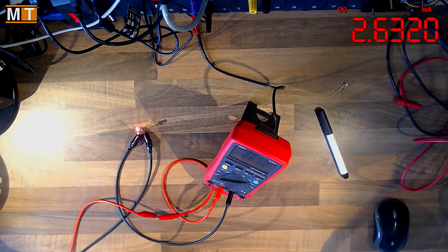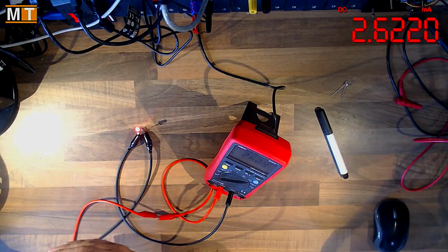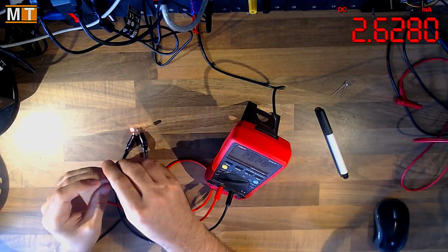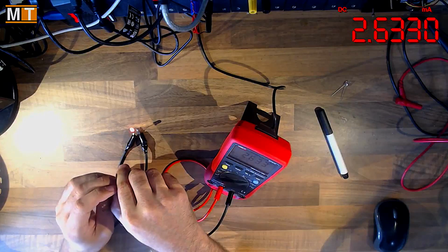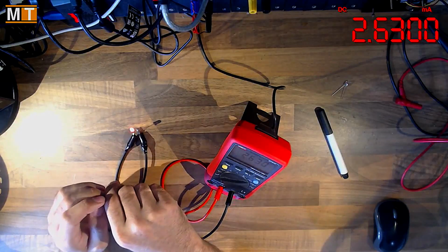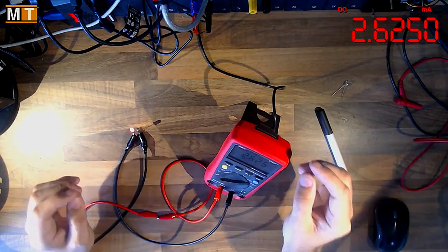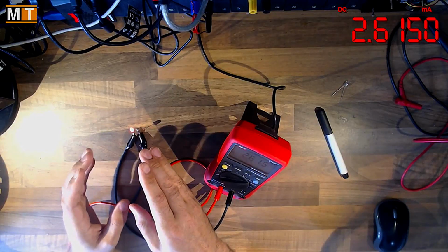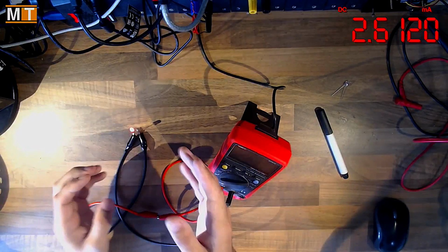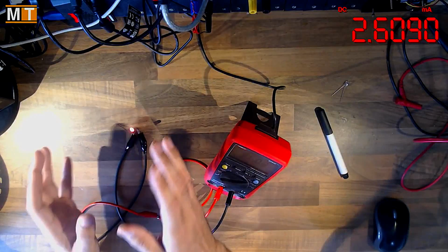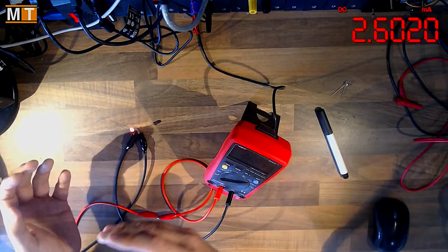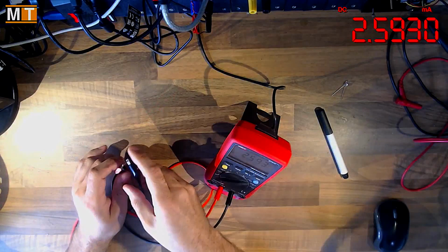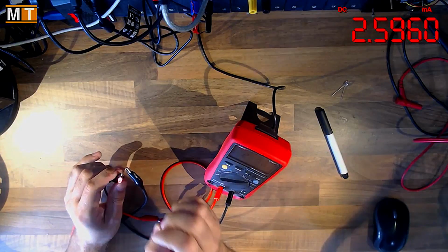Any slight fluctuation in voltage, either the voltage of the power supply or the voltage of the LED, which will actually change with temperature. As you can see on the screen there, the current is changing all the time as the voltage varies very slightly. It's not a steady constant value. The temperature does affect the voltage, the current affects the voltage, which affects the current. It's all interrelated. As the LED warms up, its forward voltage will vary slightly, which will change the current. And you risk getting a cascade effect, where eventually the current will just become too high for the LED and it'll go pop.